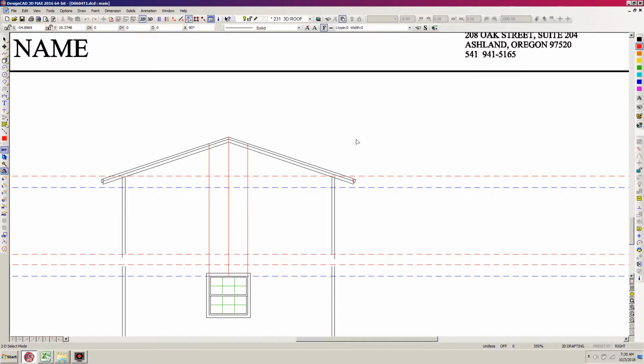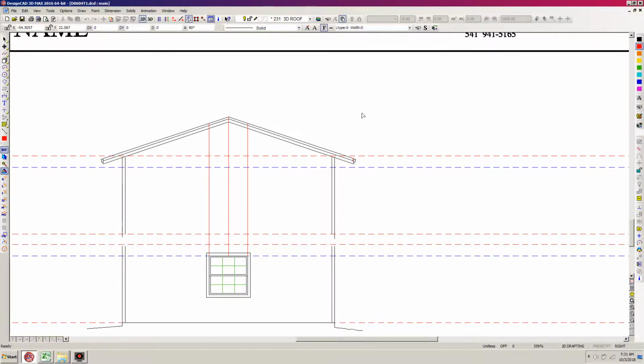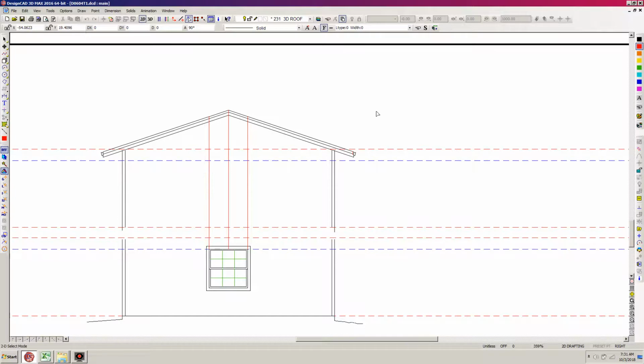We're now on DCAD lesson 22A, and we've done our preliminary work on the structure, and we're going to now be dealing with floor plans. And in order to do the floor plan, there's some additional information we need to address. One of the things that I did find out is I did a preliminary wall bracing on that front garage door, main garage door wall, and it does not meet the minimal wall bracing requirements, so we may require engineering, probably involve some hold downs, but we'll get into that a little bit later on in future lessons.